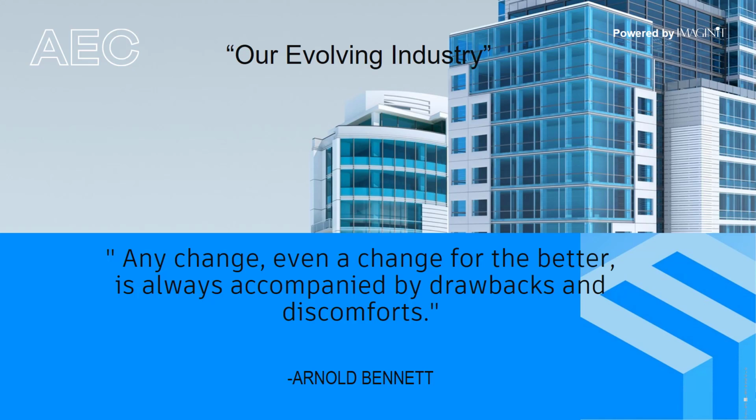It's going to have a few discomforts, like, hey, how do I deal with my detail library? So the short-term answer to that is use them, right? They're still good. Go ahead and link them in, leverage what you have. The drawback is that they're going to have to be created at some point, or recreated at some point inside of your Revit environment. So the more that you can do recreating these things, or creating them from scratch, or building a new library as your projects move forward, the better this is going to be.